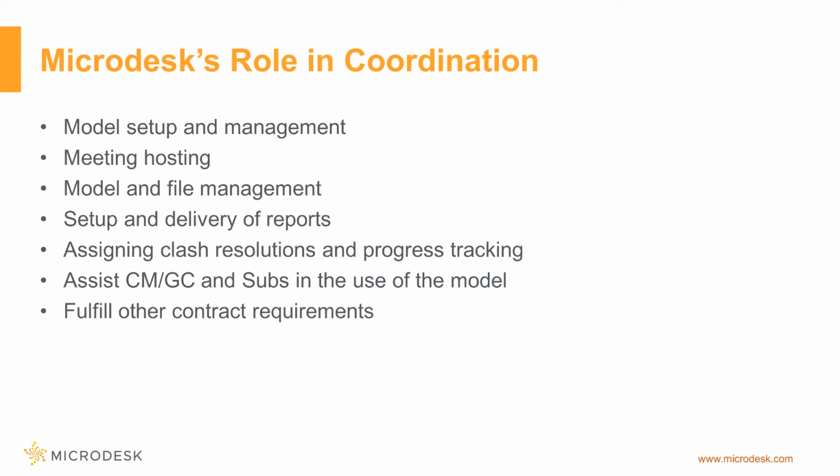So hosting meetings, so we host meetings sometimes live, sometimes over a GoToMeeting like we're on now. Go through that model, go through the clashes, track those clashes in the reports that I showed. Model and file management, so keeping track of all those different models and those files. Setting up and delivering those reports, really keeping track of the process and the responsibilities.